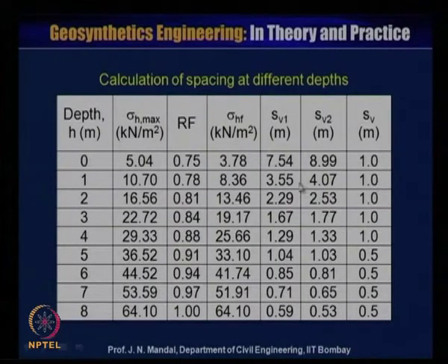So, you have to select, as I mentioned, a spacing less than or equal to 1 meter. So, you cannot adopt this. You can adopt this spacing between the reinforcement: 1 meter, 1 meter, 1 meter and 1 meter, this also 1 meter, and this also you can approximately consider less than 1 meter, 0.5 meter.